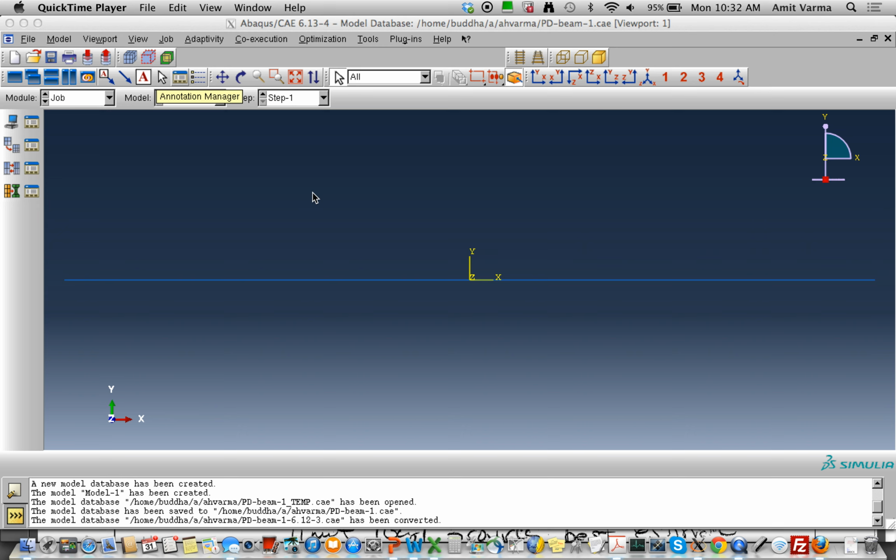So we've had a lot of fun looking at the section moment curvature response. We understand that the section moment curvature response depends upon the axial force. We understand that you can obtain it by developing a moment curvature program that accounts for plane sections remaining plane, assumes the centroidal strain, increments the curvature, and all of that. And we realize that the moment curvature can be idealized or can be understood.